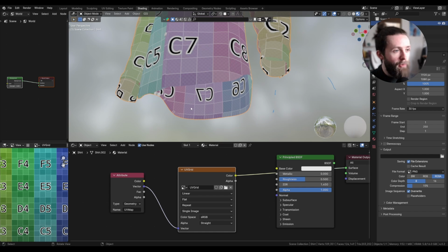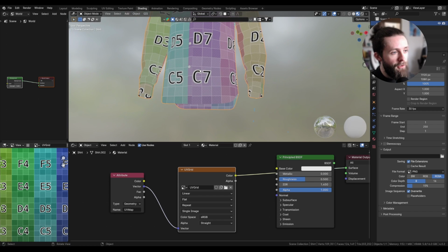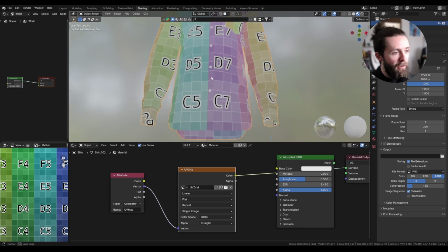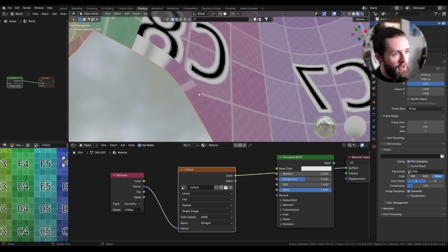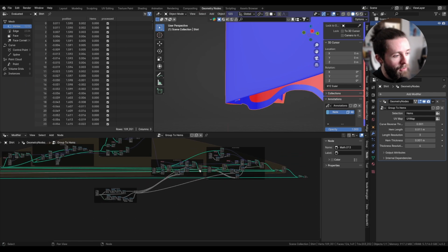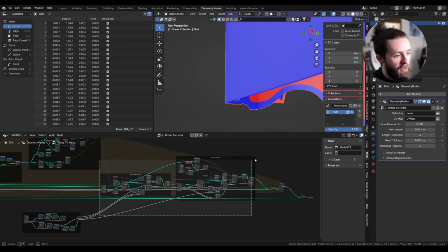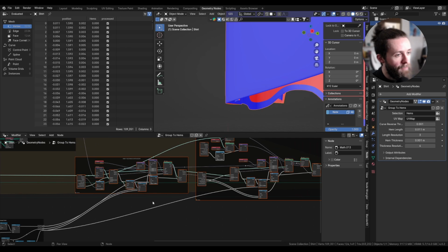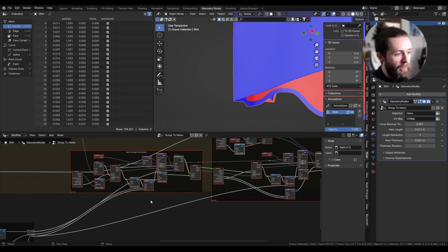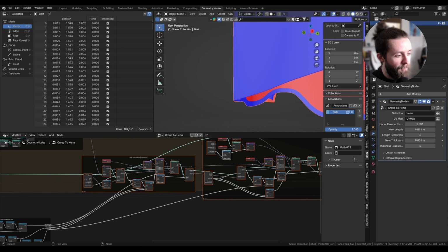So now, if your model was set up correctly, you should be able to see the UV grid properly everywhere, except on the newly created hems, where it should be really stretched. And now, the trick to get it correctly on the hems is really simple. We are just going to do about the same extrusion step, but on a version of the mesh that was put in UV space. And then by sampling the index, we should be able to transfer the UV coordinates from the unwrapped mesh to our original mesh.